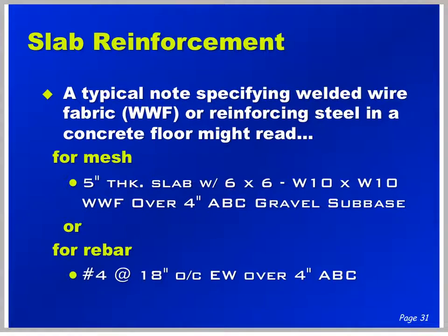The 6 by 6 is the spacing of the wire. The W10 by W10 is the gauge of the wire. And WWF stands for welded wire fabric.